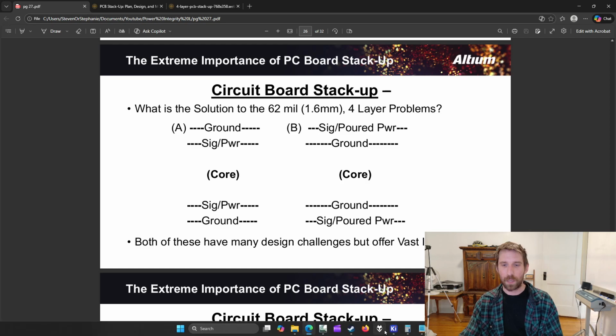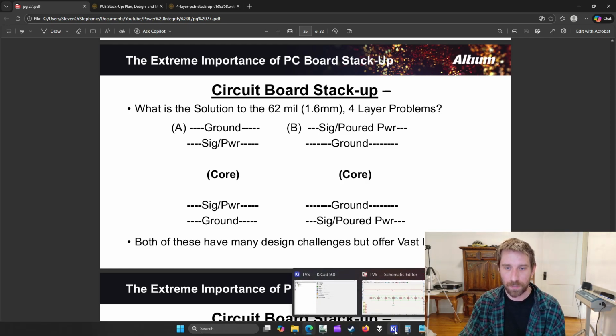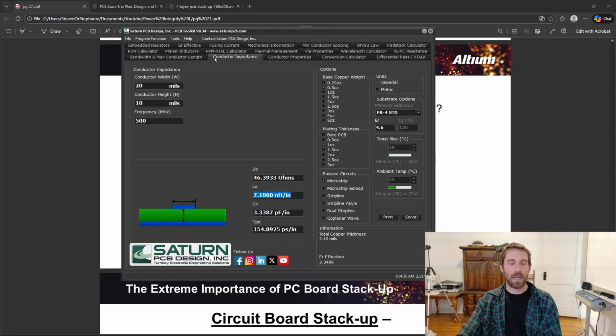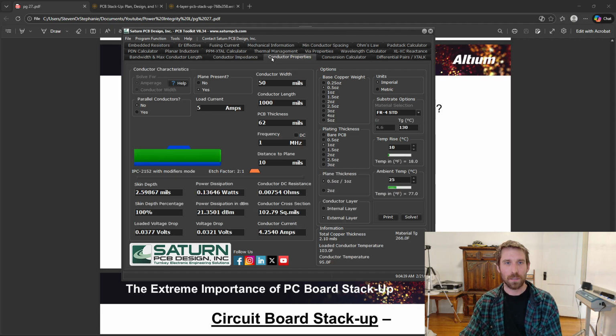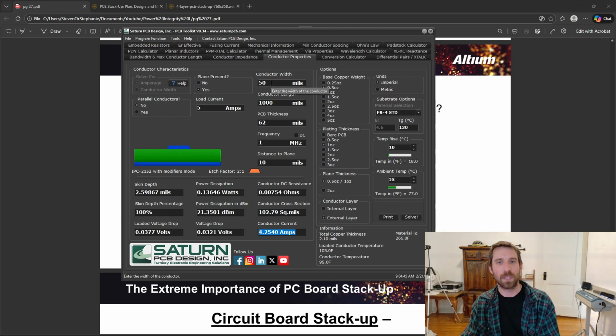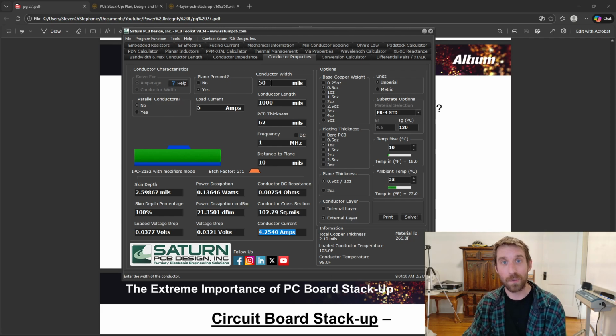So, and let me even show you why. So we got to go back to here. I have got a design where, this is where we're looking, by the way, where my fault current was 50 amps. You are, in your designs, you are checking fault conditions, right? Fault current. Good, easy example I do all the time. If I've got a motor in my product, I stick a screwdriver in there and stall the motor and see what happens. Because you know some dumbass is going to stall the motor somehow, some way. So we got a plan for that.